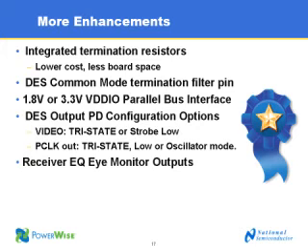We mentioned a little bit earlier both a 1.8 volt VDD-IO as well as 3.3 volt. And this is done for a couple of reasons. One is to take advantage of a lower interface level, better compatibility with the downstream device, and if you can run at the 1.8 volts, again, that lowers the EMI.